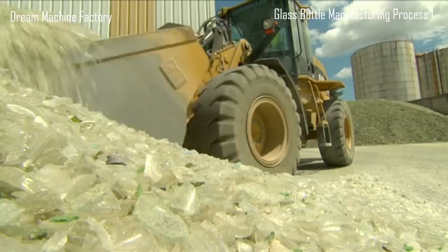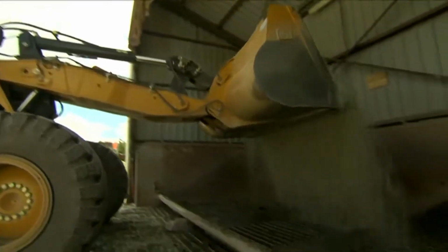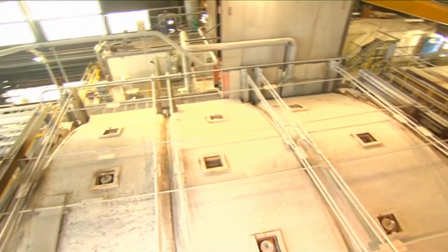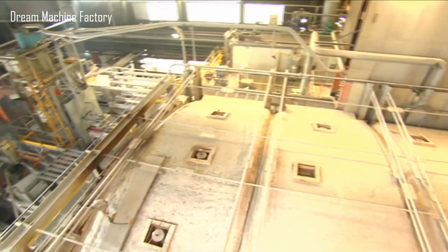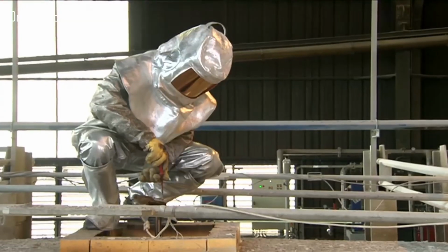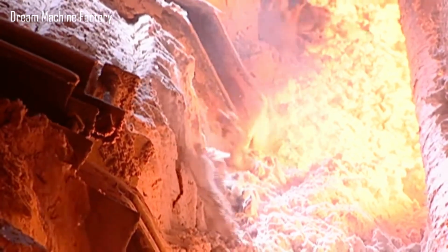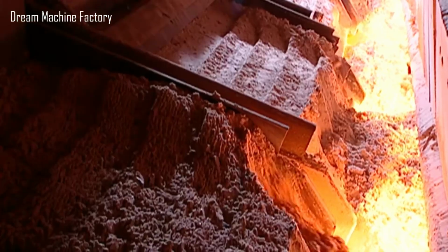The glass manufacturing process begins with a carefully measured blend of raw materials: sand, recycled glass, known as cullet, limestone, and soda ash. Recycled glass is a crucial component, as it reduces the need for virgin raw materials and lowers the energy required for melting. The mixture is fed into a furnace operating continuously at about 1,500 degrees Celsius, where it is transformed into molten